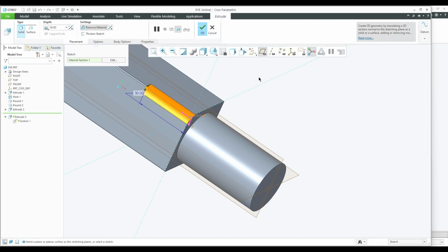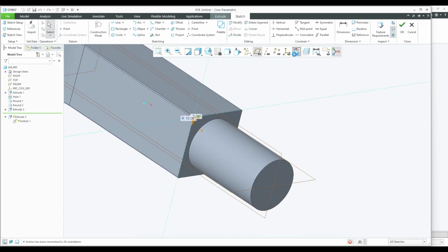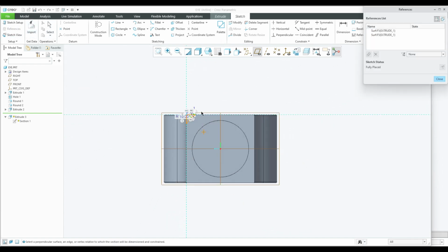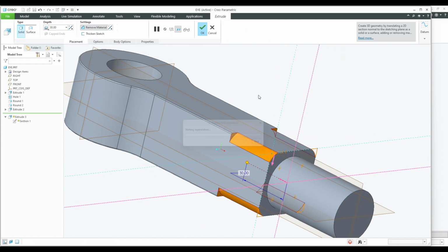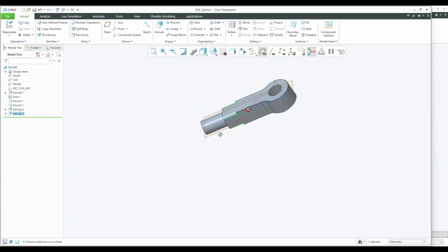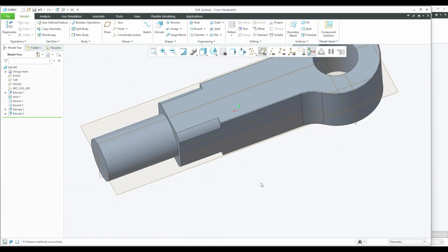Now I just want to mirror it for all the portions. Even you are able to mirror using the outside tool, I'm going to mirror it in the sketch workbench itself. So I'm going to select this center line and apply on horizontal and vertical. Select this area, click on mirror, select the vertical line, and you will get it on the right-hand side. Select the entire thing, select the mirror and click on the horizontal line, you will get it on the bottom as well. Now you can click OK, and the distance has been measured, so you have got this cutout here.